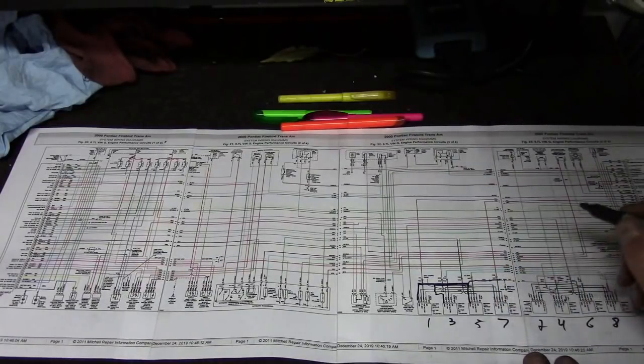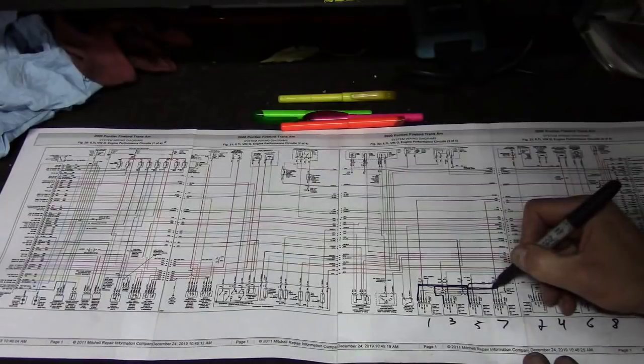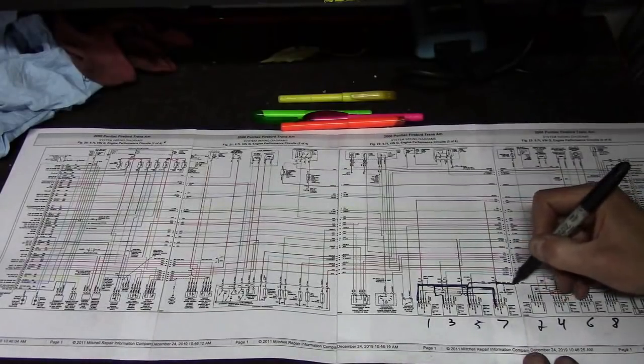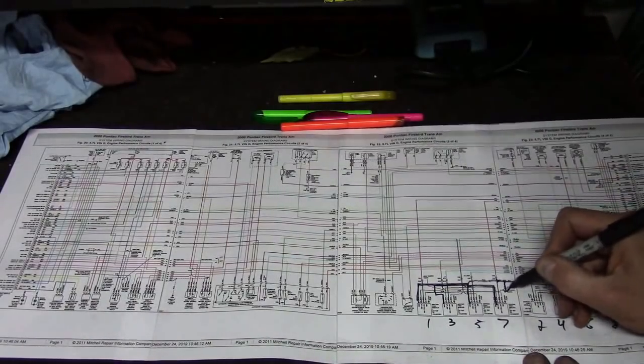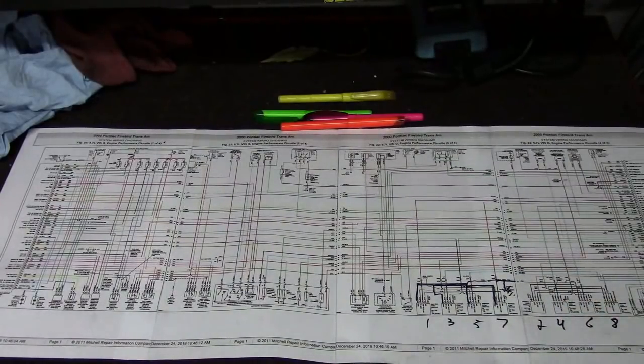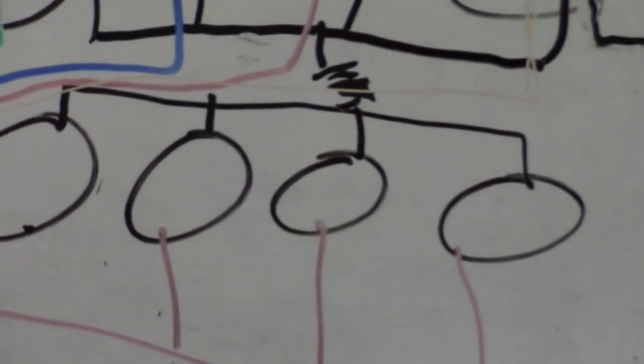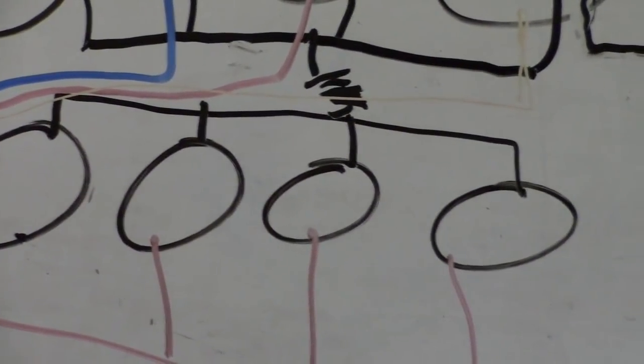And it goes off here. Oop, missed another split here for number 7. There's a ground there. And it goes off here. Right here is our ground. It actually says left cylinder head. Remember in my drawing over here? That ground right there is a fixed ground actually on the engine. Okay? So far we're looking pretty accurate.